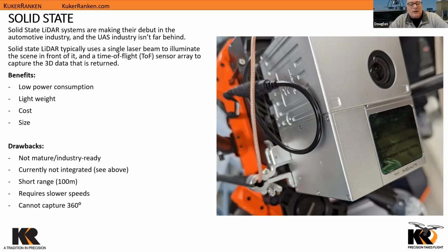However, we are seeing LiDAR systems that can do quite a bit more. The one that you're seeing off to the side here is a MapTech drone system made in Korea, and on it is the Livox solid-state LiDAR system, with low power consumption. It doesn't weigh anything. This is being picked up on a very small platform drone. The cost is really effective when we get into solid-state LiDAR, and the size is about equal currently to the size of a typical mechanical LiDAR system.